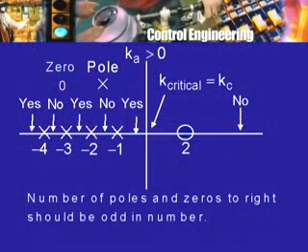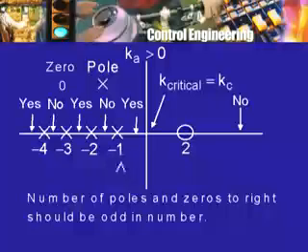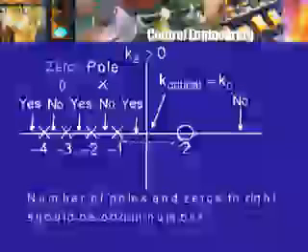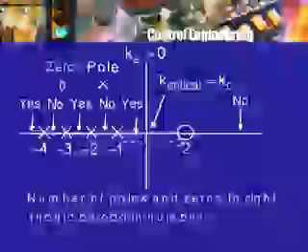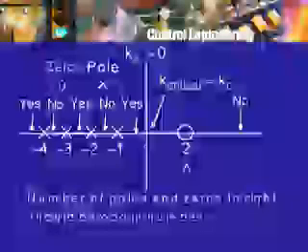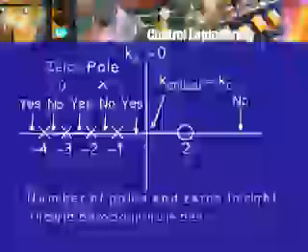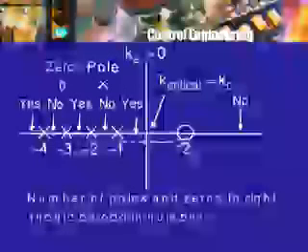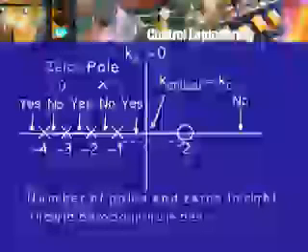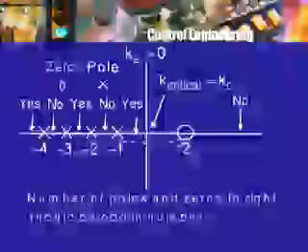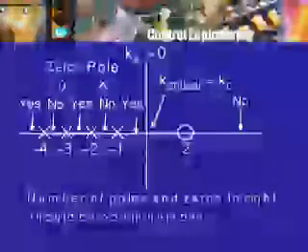That is the rule that would enable you to check that in our example the root locus branch which leaves at -1 goes in the direction of the positive real axis, and therefore the assumption that it goes along the real axis is a good one. Similarly, the branch which arrives at 2 arrives at it from the negative side of the real axis, so that part is okay. Further, we know that all the points between these two are on the root locus for some value of k or the other, and therefore it is a reasonably good conclusion that this whole segment of the real axis is on the root locus. Not only that, it is a branch of the root locus. As I told you, the root locus method is what may be called a qualitative method.